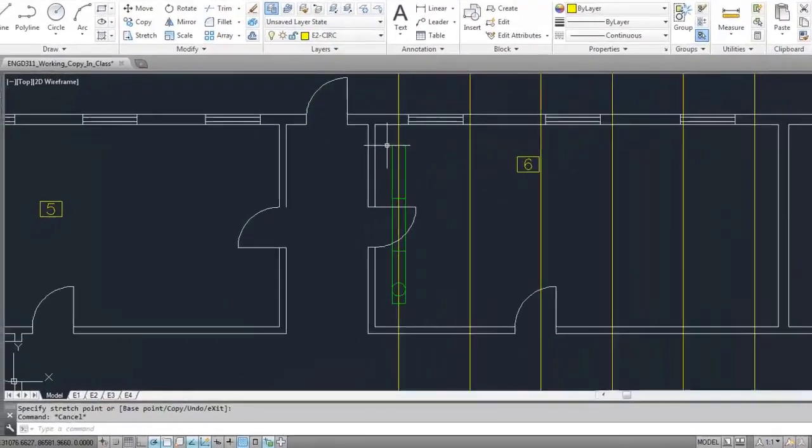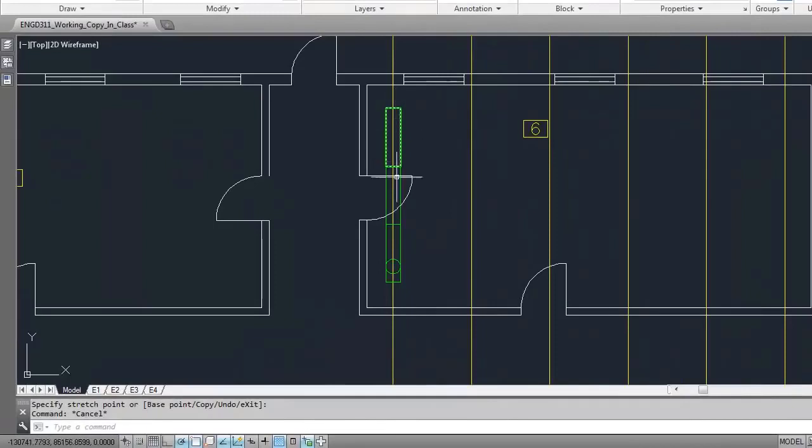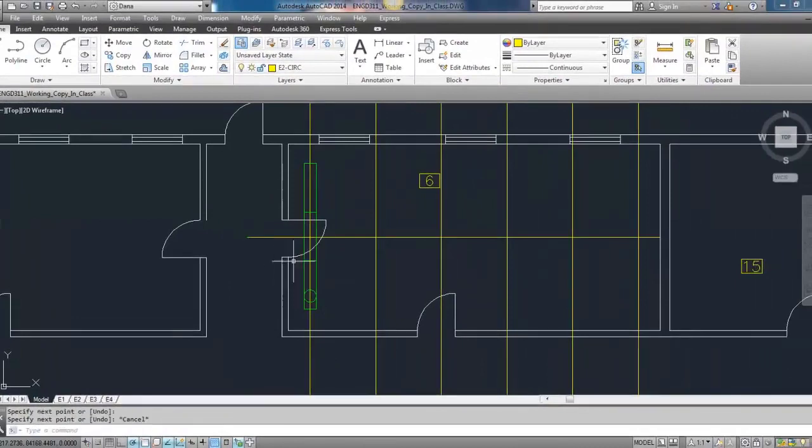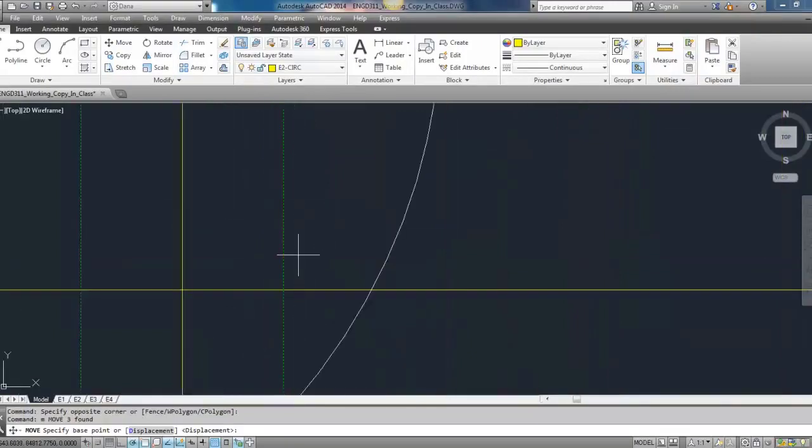Now this isn't perfectly centered. We need to be able to perfectly center that group of luminaires, those 3, in that space. So we want an equal space at the ends on either side of the luminaire columns. The way we're going to do that is we're going to draw a line from the center of the room. So if I can find a point that's from the center of the room, I'm going to draw a line straight through. And now I'm going to center this group of luminaires to that line. So I find the midpoint of my luminaires.